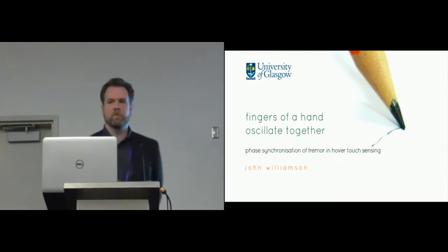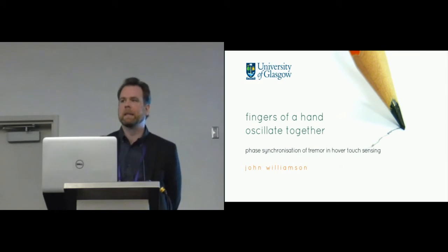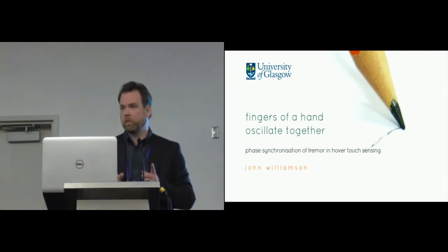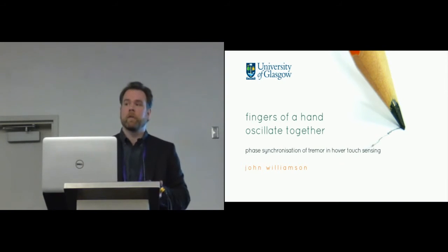Well, sensor noise is very small compared to the tremor signal. So in the measurements there, we had about 100 micrometer diameter of that noise ball. You're probably talking about 1 or 2 micrometers for the actual noise on the tracking there. So the accuracy of the device is sometimes relatively low because of poor calibration, but the precision is pretty high. So we have very, very low measurement noise.